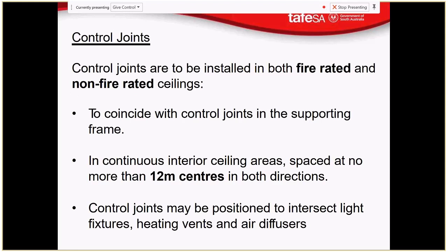With plasterboard being fixed to all our other joists, and that being able to take some tension, this joint is going to crack, or if it's really well fixed, we'll get a crack back here or something like that. But this joint will crack in a fairly random or seemingly random fashion, and it will look terrible.